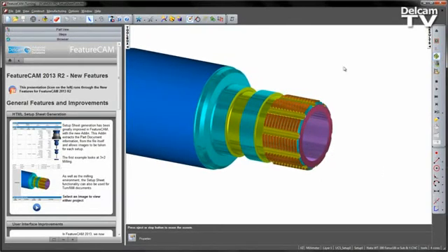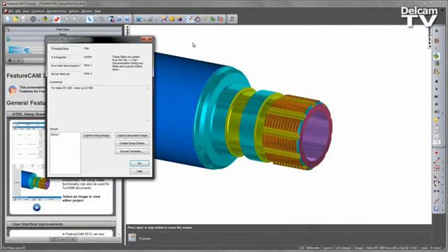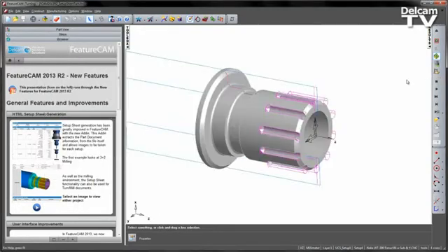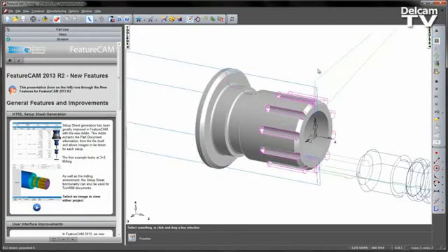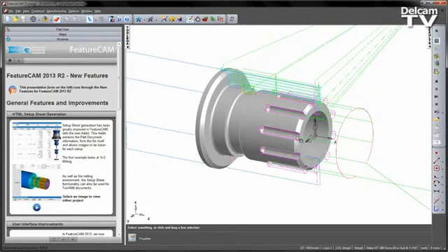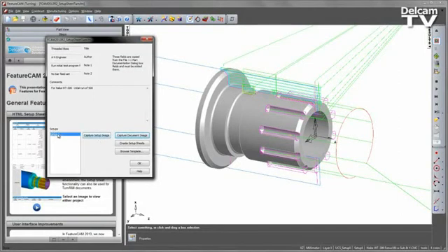The setup sheet system works exactly the same as the milling document. I'm going to click on the setup sheet icon. Note that we've already populated the fields and the part documentation with some useful information. I'm going to repeat the same process. In this case, I'm going to capture the document image. I'm also going to go ahead, stop that simulation and play the centerline to capture my setup. I only have a single setup in this instance, so I can just capture the single setup like so.